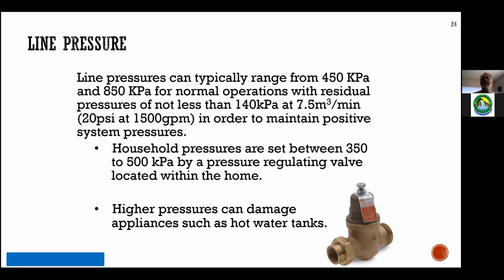Now, on the other hand, you don't want too much pressure either, because that can damage not just your customers' plumbing, hot water tanks, and fixtures, but at high pressure, it actually shortens the life of your pipeline. Because imagine high flows moving through a pressurized water system, and the higher the pressure, and we'll talk about thrust in a little while, when water changes direction, the effects are even greater, amplified, and it starts to shorten the life of the pipeline.